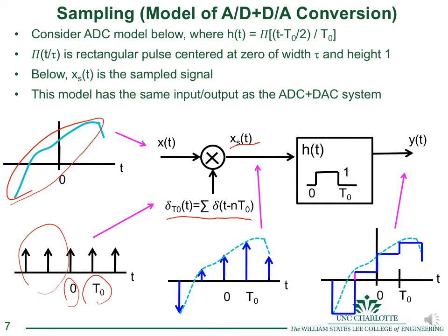And here we've just shown the multiplication and indicated that the weights of each of these impulses is proportional to the original continuous time signal. Of course, they're infinitely high, but the area is set by the weight, which is indicated by the drawing of the height of the arrows. But remember, it's the area that's established, not the height, which is infinite in all cases.